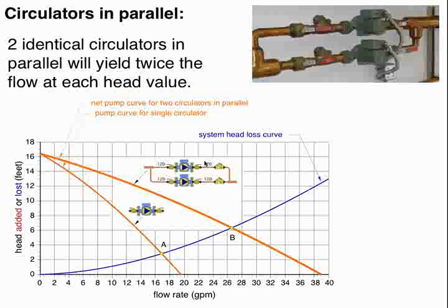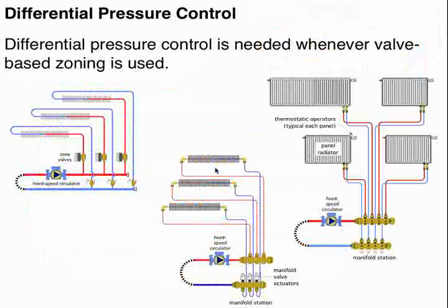It is important to put those check valves in. I will encourage you to have at least 12 pipe diameters of straight pipe between the discharge of a circulator and the inlet of any check valve. That's so the check valves don't rattle. If you put the check valve right on the discharge of the circulator, you're getting turbulent flow coming out of the circulator at times, and that'll make that check valve rattle. Ask me how I know that.